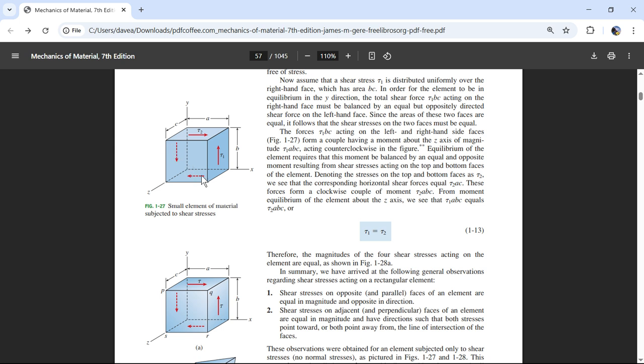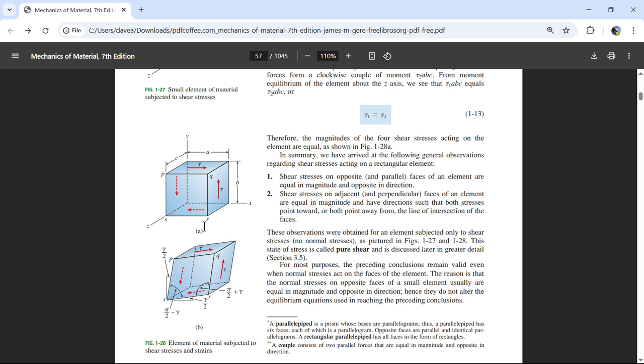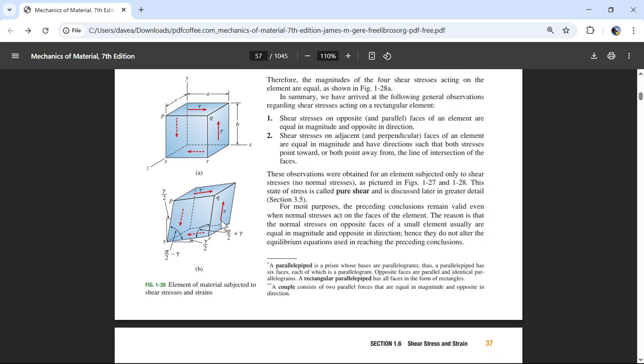So whatever that shear stress is, I know the force is the shear stress times that area, but the area is much bigger now, and so it's going to impact equilibrium. So now you can look at these as stresses or forces being applied on those areas, and we're going to have all these equal and opposites. So these two are going to be equal. If this is up, the other side has to be down. And that's going to cause a torque, and then these have to be countering that torque.